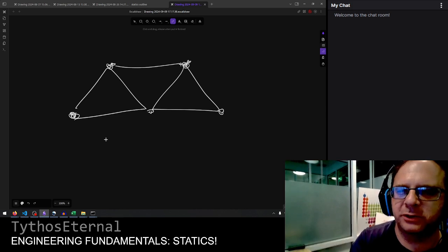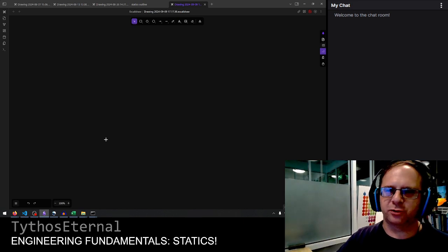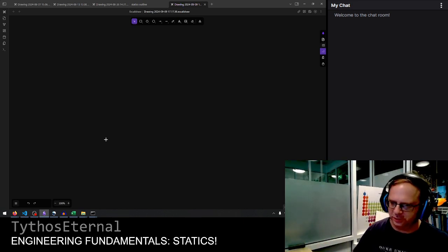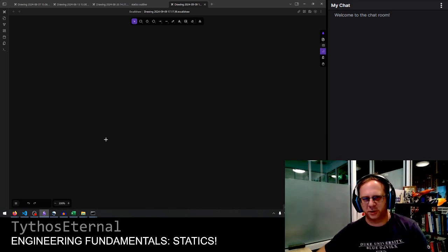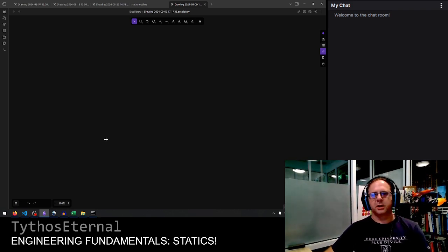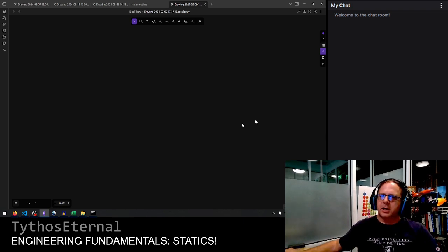And if it's a determinate system, you have some guarantees that eventually you'll be able to know anything you want about that system. And that's true for trusses. That's true for arbitrary combinations of pulleys and tires and screws and frictional belts. Forces and moments and displacements and angles, all of those things just combine into the equations of the system that you constrain with a static constraint to sum all of them to zero and then solve for the individual elements.